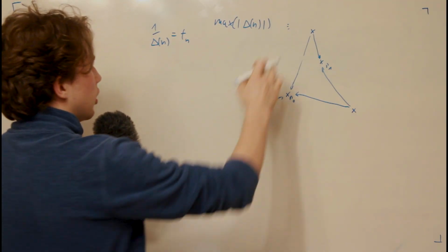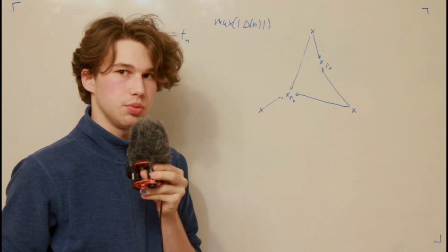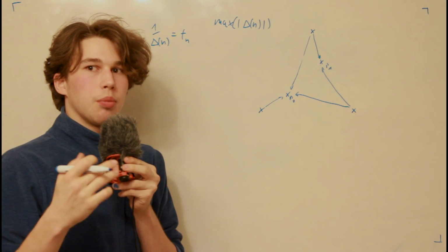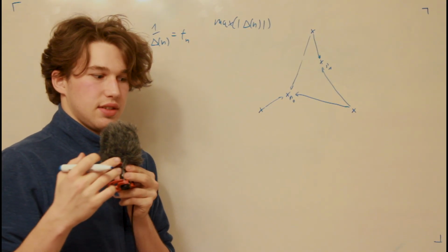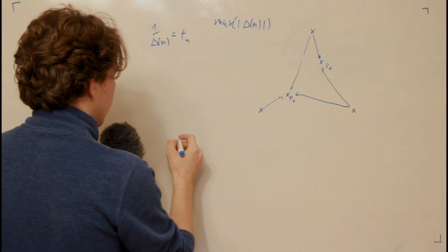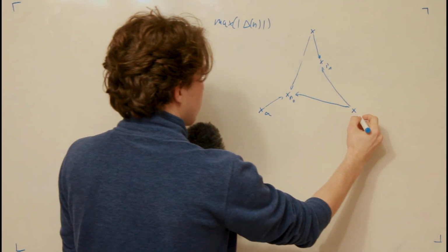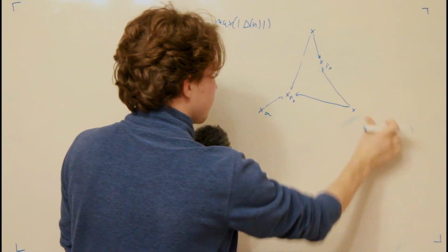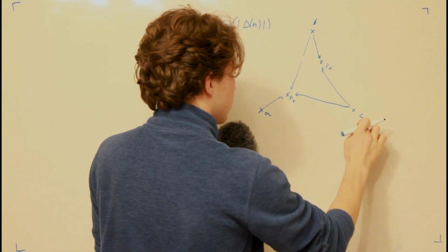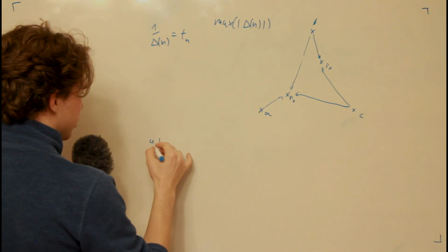Even when knowing how much we move where and how much each motor of Floaty needs to move, we still encounter a small problem. It is that our motors don't run exactly equally fast. Our motors are stepper motors and they give pulses. If we draw the steps, the impulses from a motor, they are going to look like this.